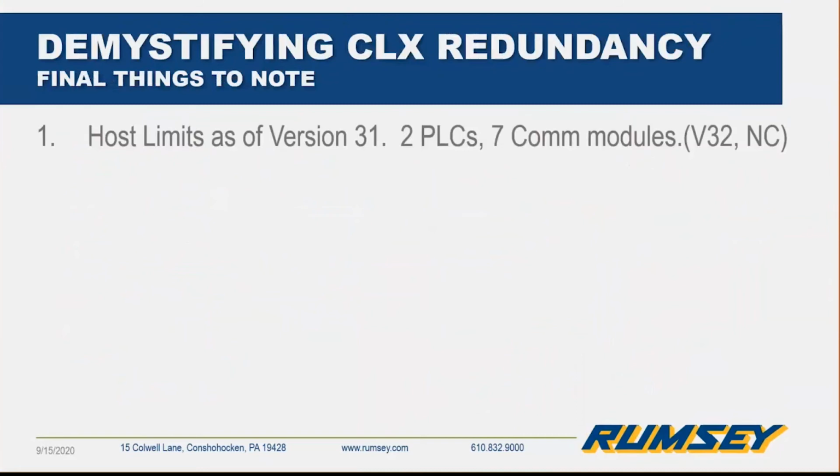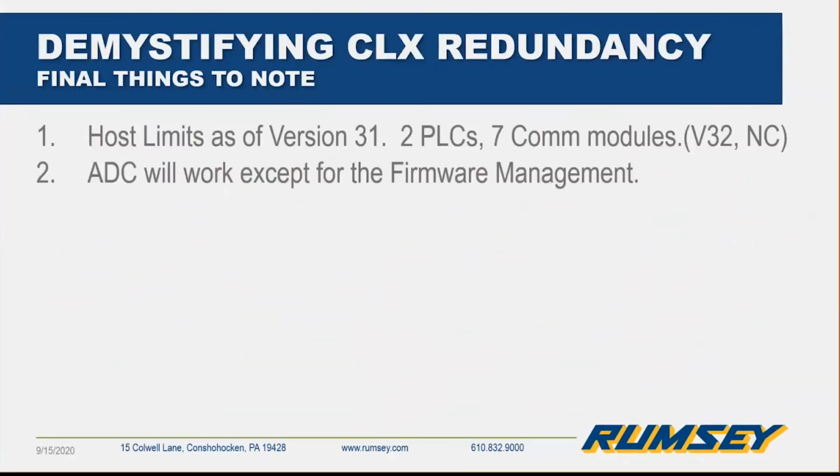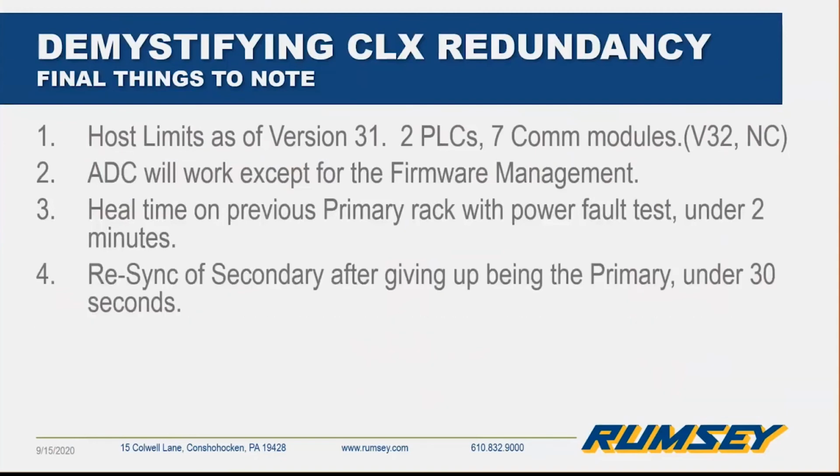Quick reminder of the limits: version 31 and 32, 2 PLCs, 7 communication modules. ADC will work except for the firmware part. Heal time: I did some fooling around when I had a demo back in March, I think it was, or February. I just simply turned off the primary, turned it back on, and it healed in 2 minutes.